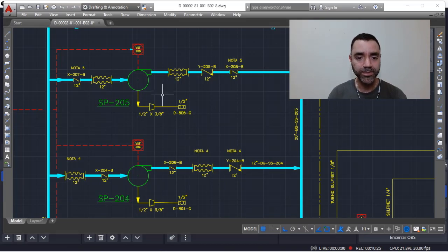Another thing to observe here, as I mentioned to you, the gas is saturated, and when we stop both machines for maintenance, eventually we can have condensate inside the machine. So in the bottom of the blower, we will have a drain valve, and in both cases they have the same arrangement.